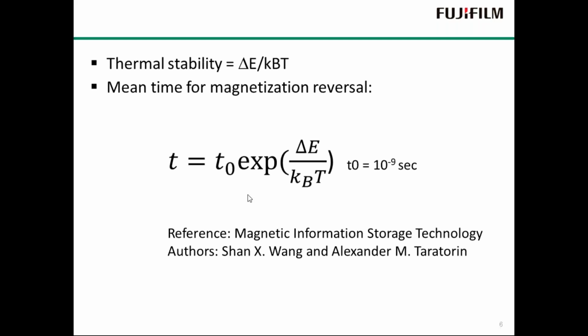Oh, I was just going to say that this is the difference between what we would call media durability and magnetic stability. For example, the Challenger tapes that went down into the ocean and sat at the bottom for 3 or 4 or 6 months, the magnetic stability of those magnetized particles did not degrade. They were still fine, even soaked in salt water. But the media itself had degraded, and there were a lot of problems trying to sort that out. So when I was talking last week about the differentiation: do you ever have a magnetic particle that becomes unmagnetized? That's one thing, and that's what Yuichi-san is talking about. Versus, would you have problems trying to read a piece of media on a drive?